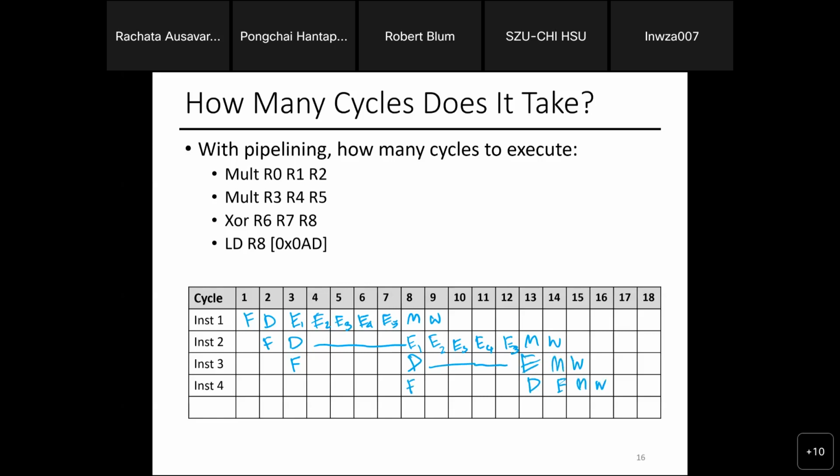Another thing from this example that I want you to be aware of: you see how write back happens in order. If I want to, I can make the design so that instruction 4, when I fetch, sneaks in and finishes the whole thing before I finish instruction 2, right? Assuming I have unlimited hardware, I can do that. Basically, it means that the write back of instruction 4 is done before instruction 2's write back.